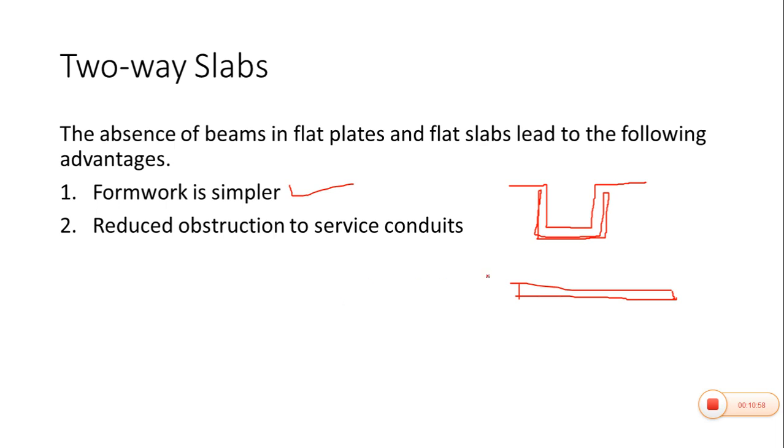Yes, in residential or commercial buildings, we need to provide water supply connections and electricity supply connections. In those cases, if we provide beams, it will require more effort as compared to flat plates and flat slabs. Why? Because we can see the example with the same drawing.